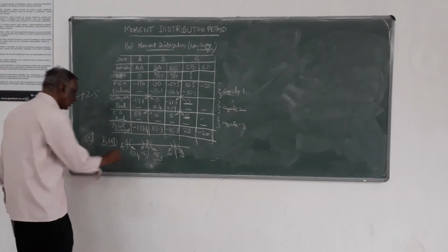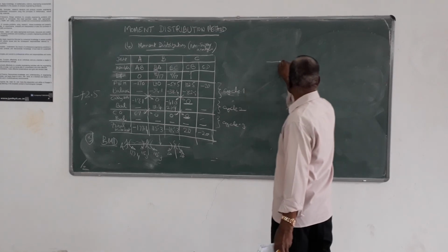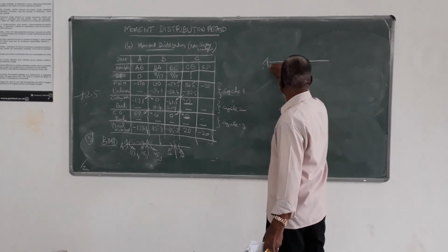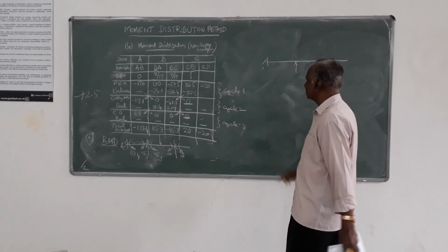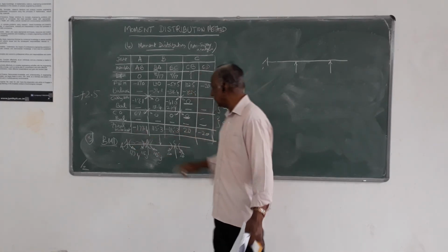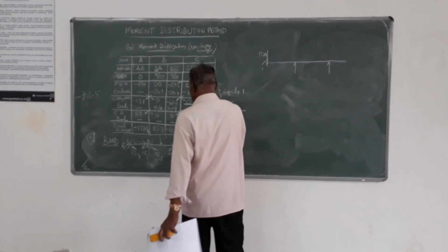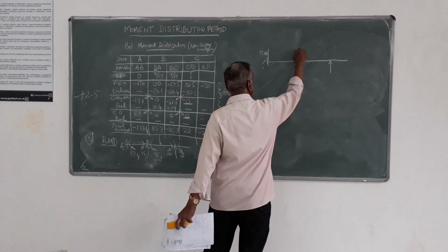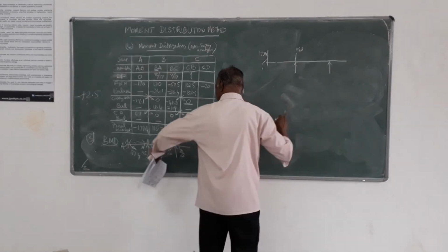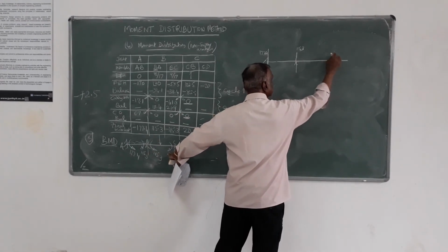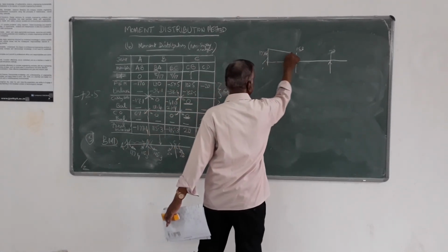That's all. Now you superpose the free moment diagram and the fixed moment diagram. You will get the actual net bending moment diagram. So here by plotting, we have to plot it on the tension side. This is 177.4. Then here it is 115.3. And here again, same 115.3. This is 20. This side also 20. So you can join this.